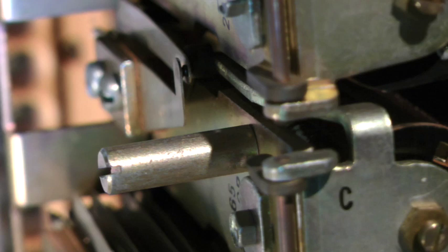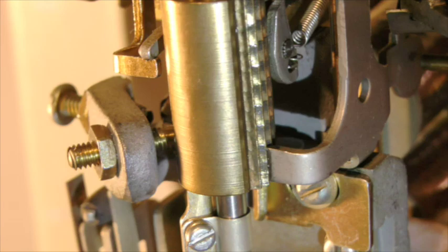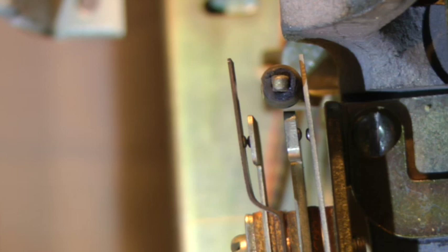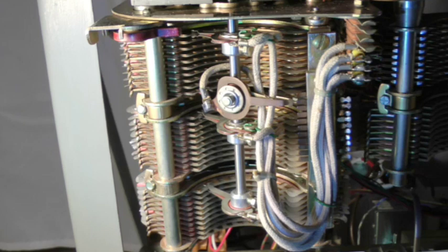This releases the C relay. With C released, the rotary magnets are de-energized, and so the rotary armature releases. And the rotary pawl disengages from the rotary ratchet. The rotary interrupter arm releases, reclosing break contacts 1 and 2 and opening make contacts 3 and 4. This ends the rotary stepping cycle for rotary position 2. Let's just watch and listen to the rotary position 3 stepping cycle.